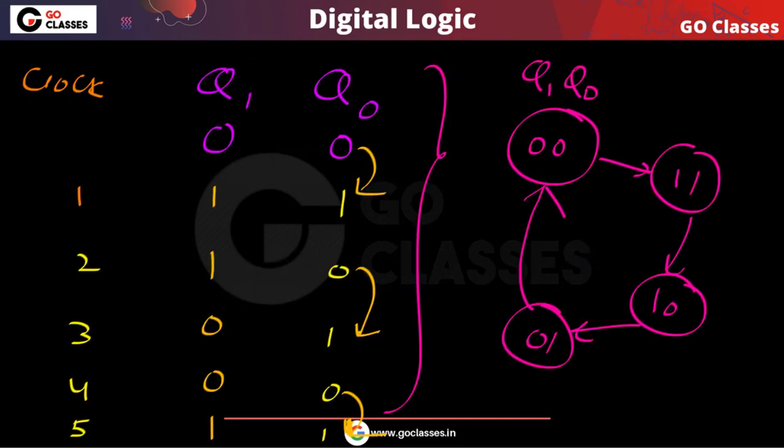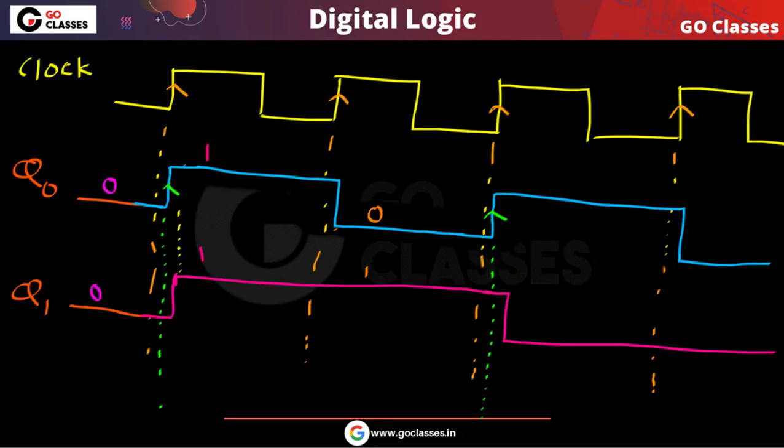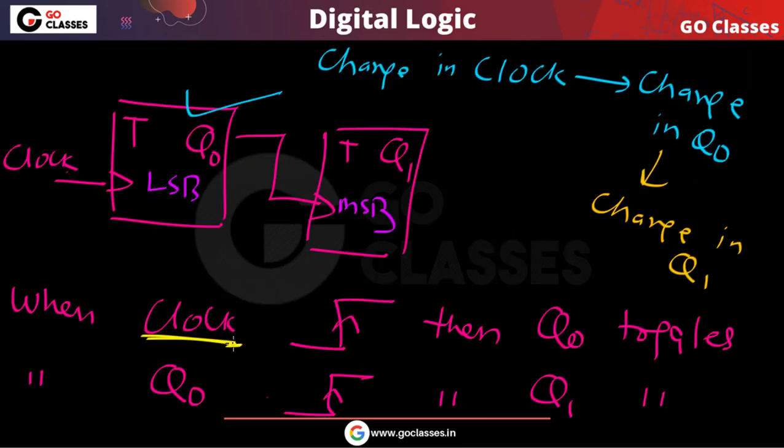One more thing you should observe. If you have more flip-flops, because of this propagation delay, you can notice this in an asynchronous circuit. The clock will control q0, and then this q0 will control q1. So first the clock controls q0, then q0 controls q1.